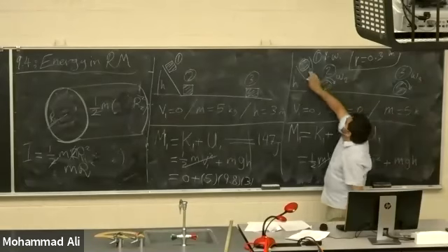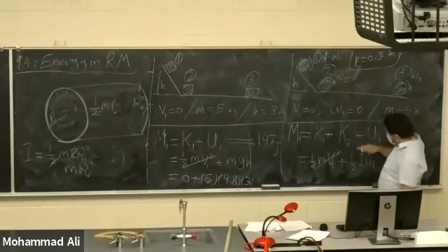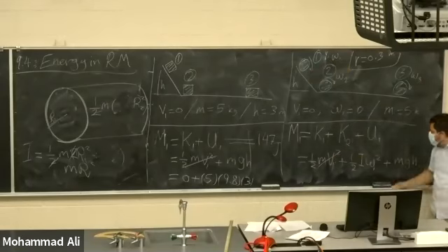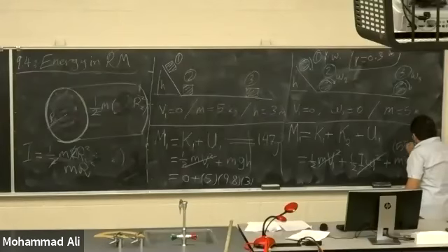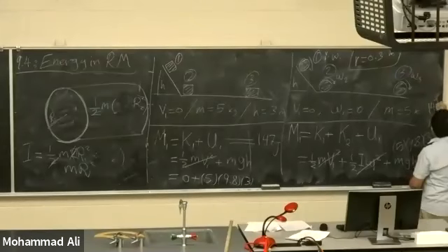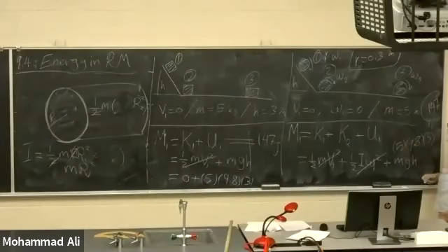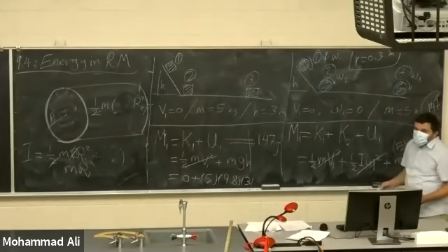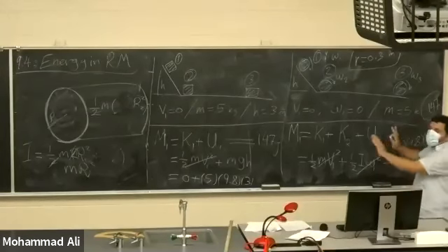The rotation now, omega 1 is 0, then the rotational kinetic energy is also 0. We have a potential energy. M is 5, g is 9.8, h is 3, the same. It is equal to 147 joules. It is the same as that system. But we have two objects. Is that understood? We have the same energy.